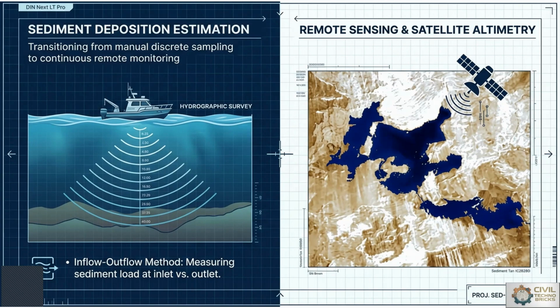This provides a real-time digital record of how sediment moves and settles, which is vital for the long-term maintenance of any type of dams or reservoirs. So, the inflow-outflow method is used for the measurement of sediment load at the inlet level versus the outlet level.